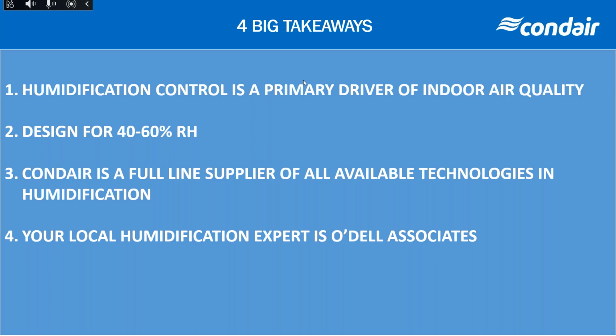So a question here, on my energy analysis, was what type of facility would have a 1,000 pounds per hour load? Are we talking a hospital or a home? Certainly not a home. A home is going to be less than 10 pounds per hour for most of us, and it's usually between 3, 4, 5 pounds per hour for residences. 1,000 pounds per hour is generally a larger industrial facility. It can be a hospital as well, depending on the size of the hospital. But 1,000 pounds per hour is going to be a large commercial building or a large industrial facility.